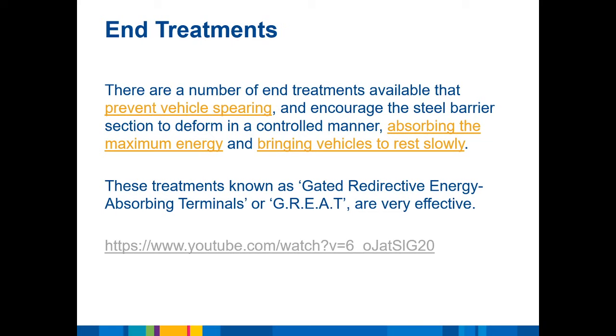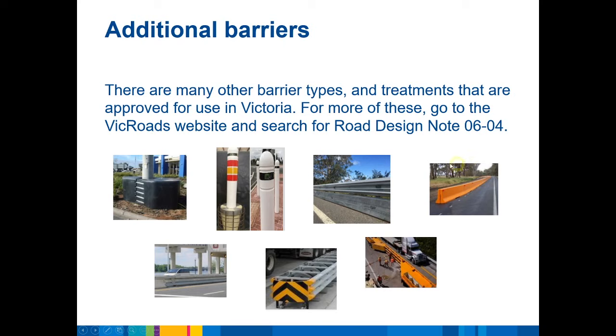Okay. All right, so there's some other barriers in here that are worth noting as well. So we've got quite a few visible. In the center here, we've got a W beam, and then underneath there's more steel. We call this rub rail. So this is put in place for motorcyclists. And again, the idea is if the motorcyclist comes off, we don't want them to hit the steel posts. The rub rail lets them slide along. And sliding, if they're wearing leathers, is quite a safe way for them to lose speed and not be injured.